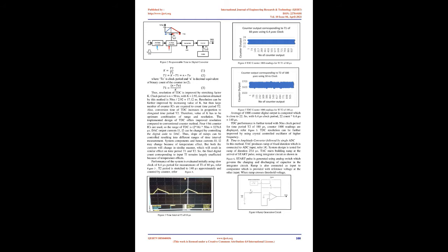Performance of the system is evaluated initially using a slow clock of 6.4 µs period for measurement of TI of 60 µs, refer Figure 3.